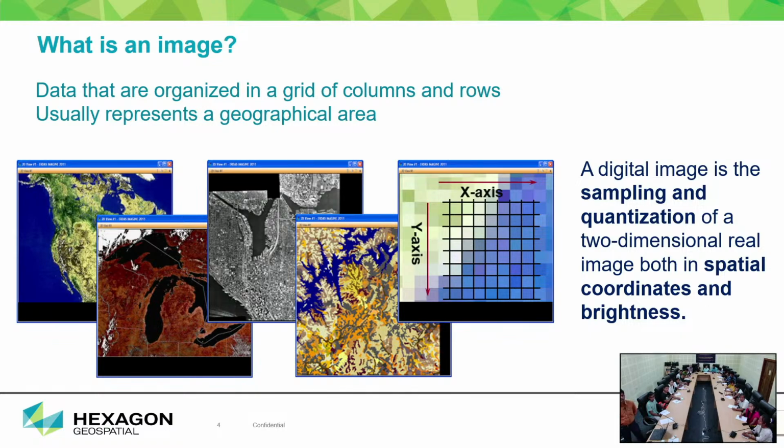So you can see there are 4 samples of satellite data. The first imagery is in true color, then the RGB, then the panchromatic band, and the last is a thematic final product we have developed using density slicing of DEM, digital elevation model data.